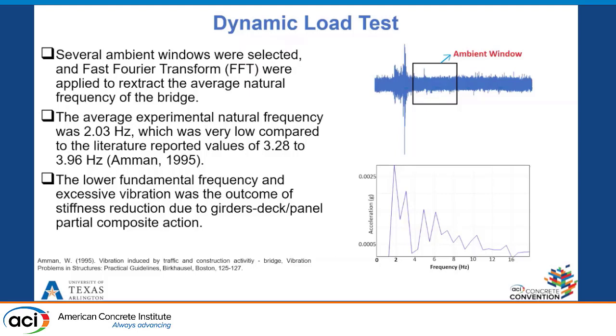The severe delamination of the deck and the partial composite action in the girder-deck system reduced the superstructure stiffness significantly, resulting in high accelerations and low fundamental frequencies.